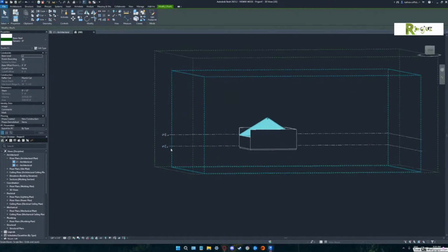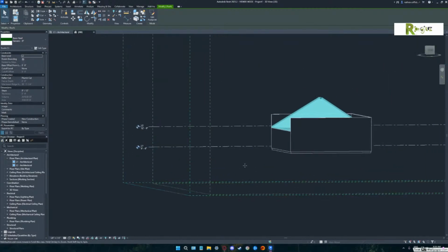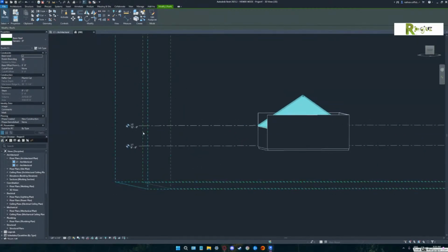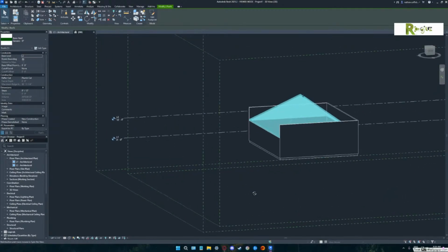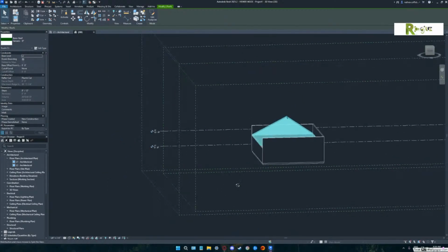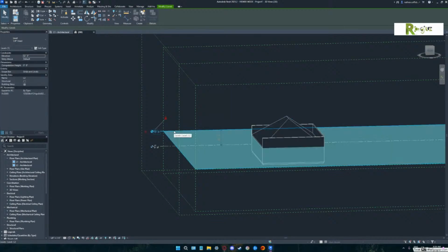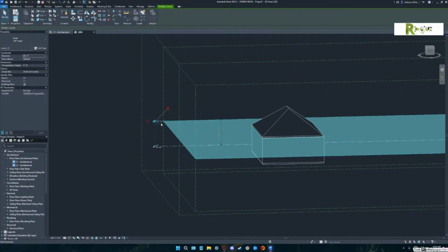And that was initially the problem I ran into as to how to move these and how to create these. Now watch, because this is going to be a common repetitive thing. If you pick on that L2 grid level line, pick on the line itself, not the number. Now pick on the 12-foot. There you go. Make it 20 feet. Watch what happens.